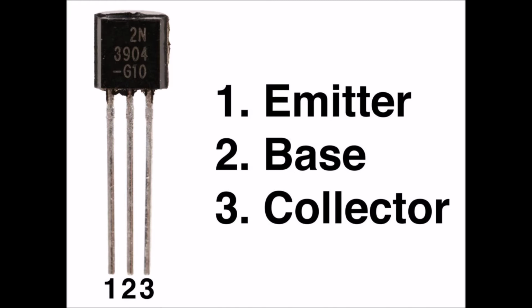Even if a circuit point remains at ground potential for signals, it can have a significant DC voltage with respect to electrical ground. In the circuit shown, capacitor C1 appears as a short circuit to the AC signal, so the emitter remains at signal ground. But resistor R1 causes the emitter to attain and hold a certain positive DC voltage with respect to electrical ground, or a negative voltage if we replace the NPN transistor with a PNP device.